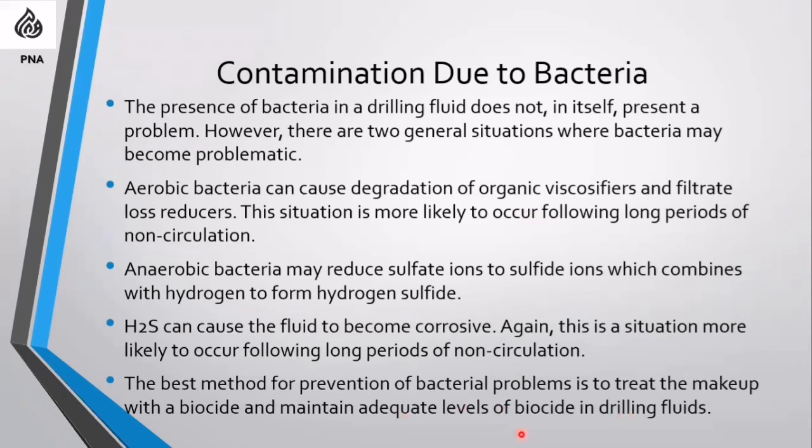Then our chemicals will not degrade, and the sulfate cannot change to sulfide and become H2S. So preventing contamination due to bacteria is easy. Just use biocide in your mud.